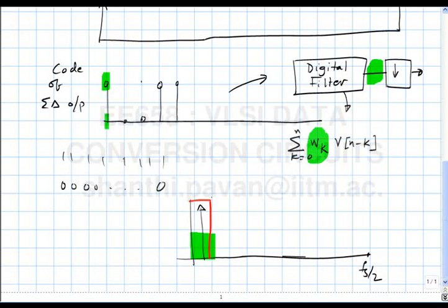Because the highest frequency component in this signal corresponds to the brick wall filter, correct? So I can actually downsample this by the oversampling ratio, and I'll end up with a signal with a signal to noise ratio corresponding to this divided by only the amount of noise in the signal band. And this noise is all coming from where? It's all quantization noise.